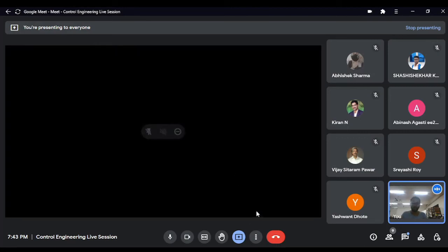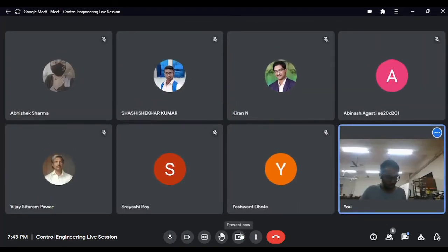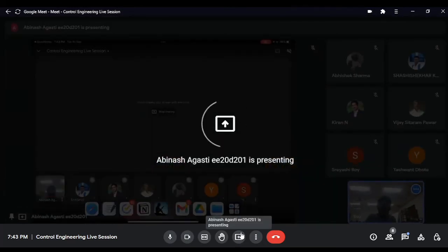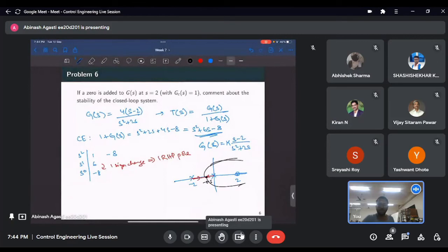Let me share this. Yeah, you can see my writing pad, right? Yes. So for normal root locus we have this. This implies kgh equal to -1, that is 1 at 180 degree. So from there we find out rules: where on the real axis it should be, what the asymptote angle should be and all that.